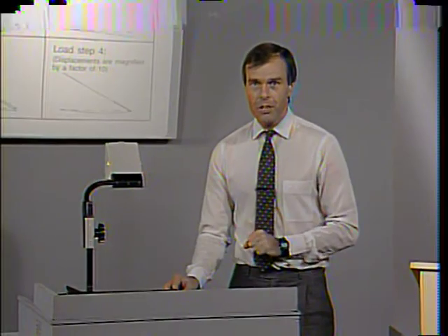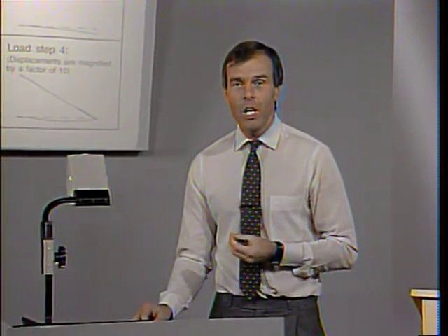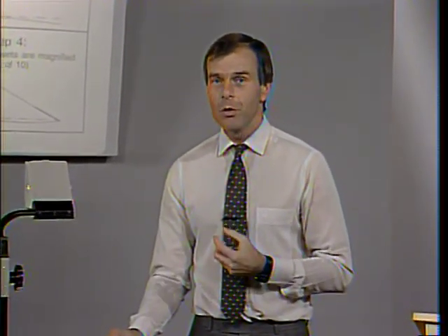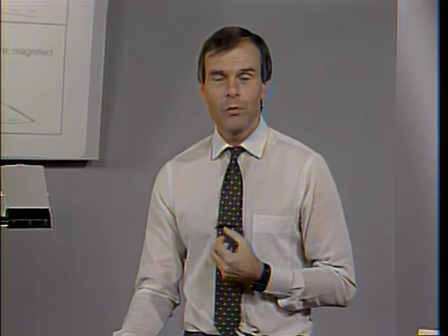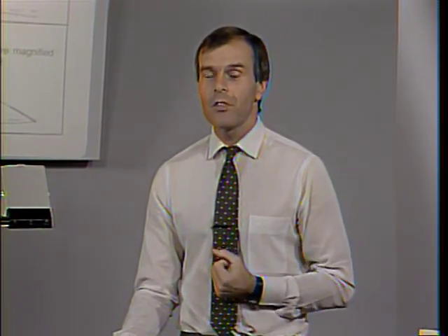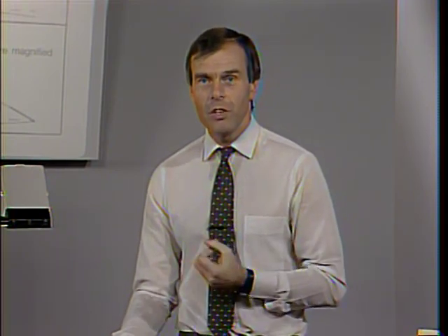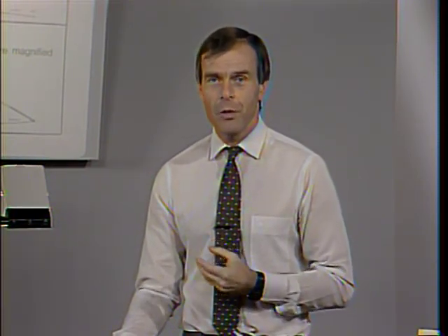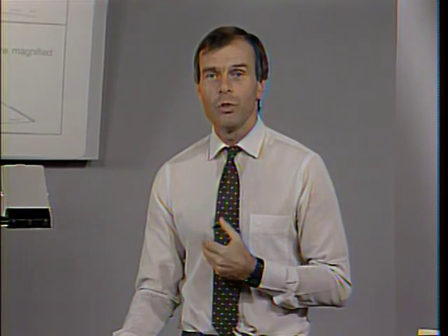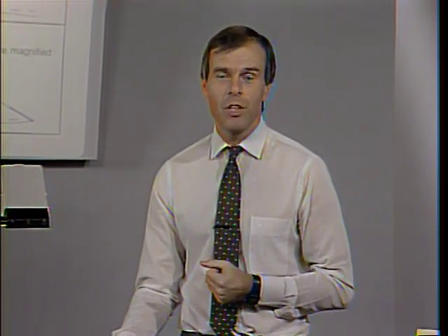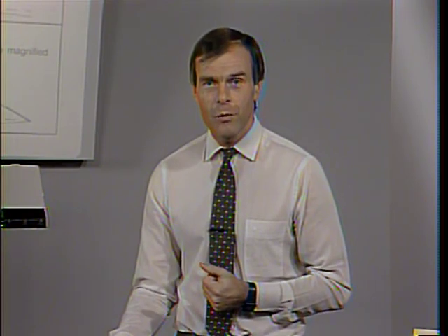This then brings us to the end of this example. I wanted to show you this example really as a demonstrative example to indicate to you how this element birth and death option can be used quite effectively to simulate repairs of structures. In an actual analysis, you of course might want to use a finer finite element discretization and also a finer integration scheme to pick up the spread of plasticity more accurately. However, this example really shows to us how we can use this element birth and death option to simulate such processes as repairs of structures, and I think you can easily visualize how this element birth and death option can also be used to simulate construction sequences of structures.